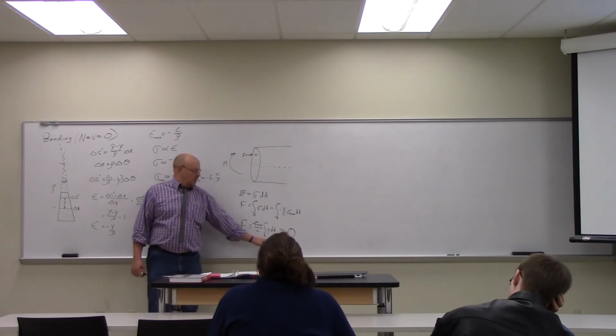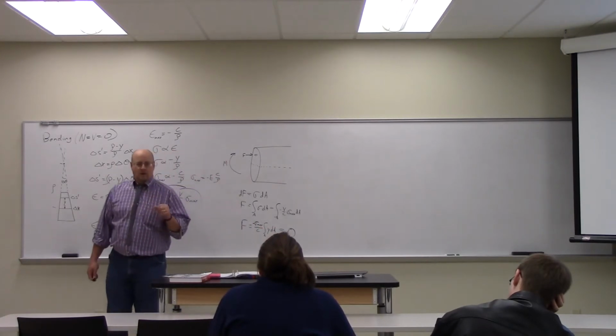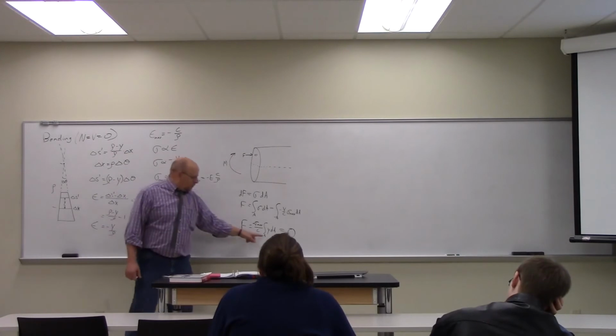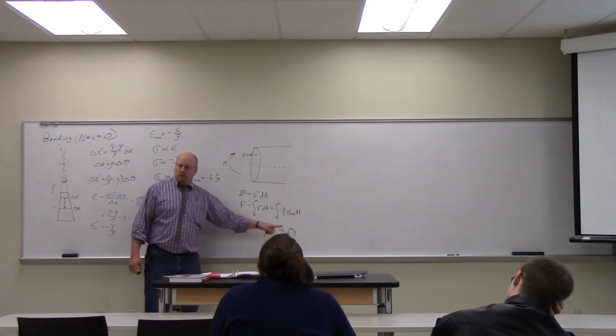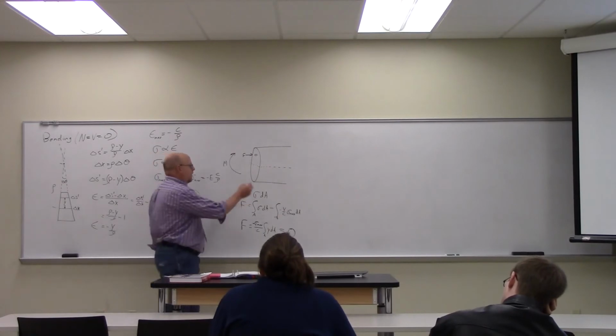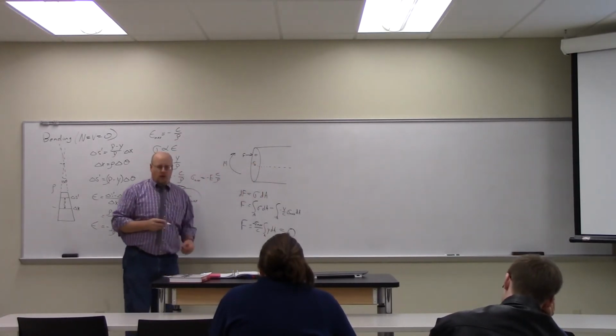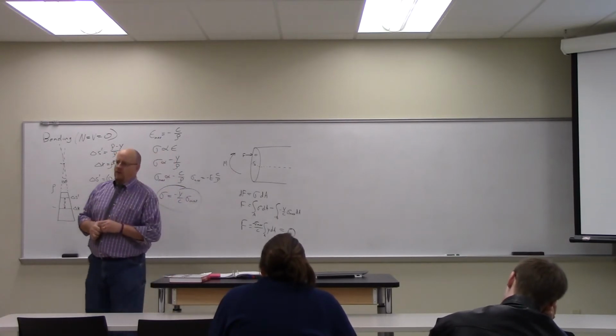When that integral is equal to 0, then we have defined our centroid. This integral is only equal to 0 when it is taken with respect to the centroid. Therefore, the neutral axis passes through the centroid of that face.